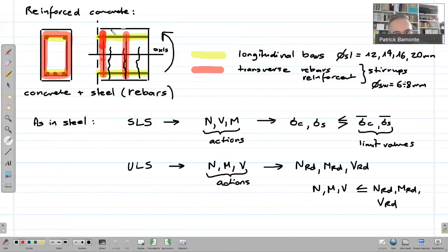The idea, which I clearly explained in this slide, is that when you have reinforced concrete, you use steel and concrete together in such a way to overcome the weakness of concrete. So where concrete is in compression, it can sustain the applied loads without major problems, whereas where it is in tension, it needs some steel reinforcement, which can bridge the tensile stresses that take place because of the application of the loads, okay? So these were the basic ideas.